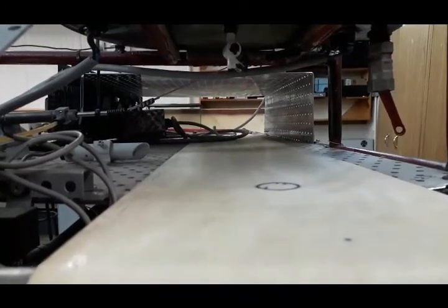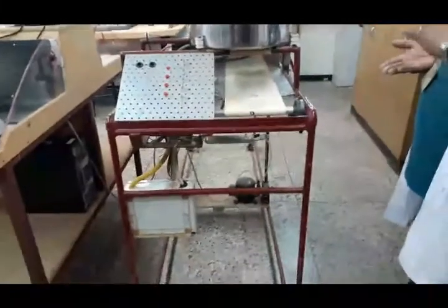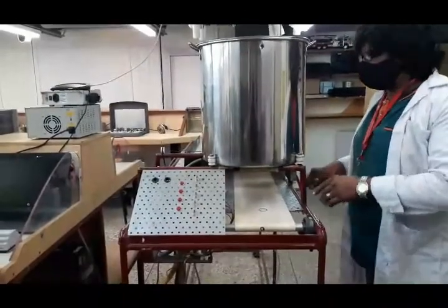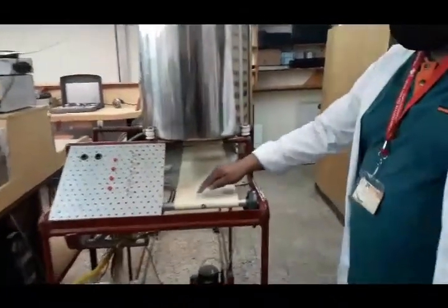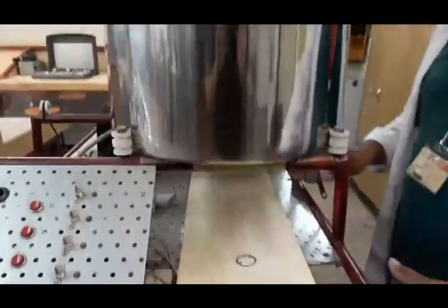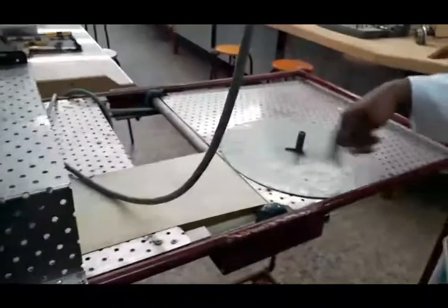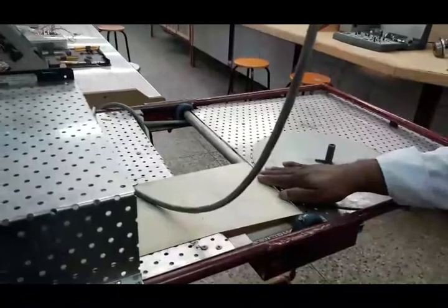The wax, based on the PLC timing, will reach a certain point, and there is a sensor, a strain gauge sensor, that will determine the weight of the wax, or the quantity of wax in the container, and it will turn back on the motor again, and the conveyor will continue running, carrying it to the coolant chamber. The next container will come in place here in preparation for the wax to be poured in. The container is conveyed to this section here that rotates, and it will take it away or clear the entrance for the next completed wax container.